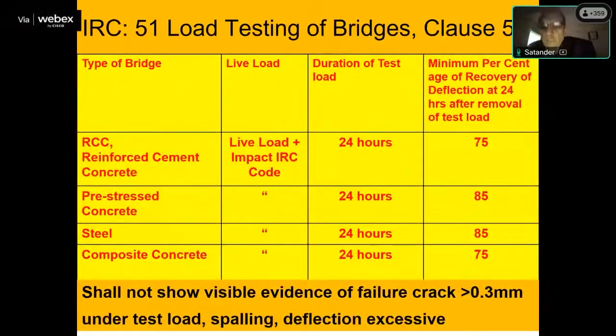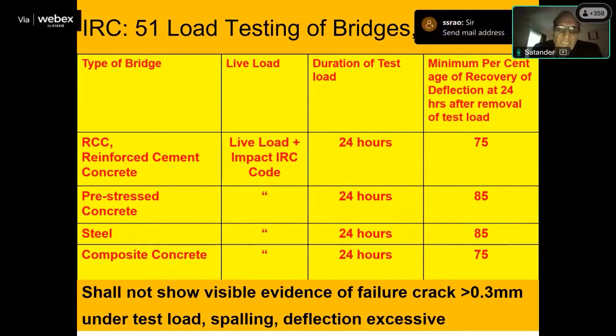First, sir, this is your IRC 51 code. There are 2 codes, IRC SP 37, that is also load testing, and IRC 51, that is also load test. What is the difference? IRC 51 is testing of new bridges. IRC SP 37 is load testing of the old bridges to find out the rating.